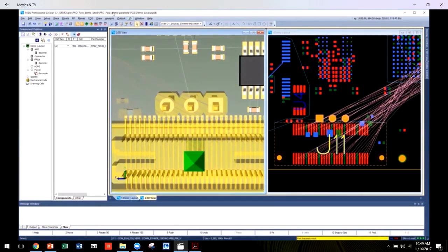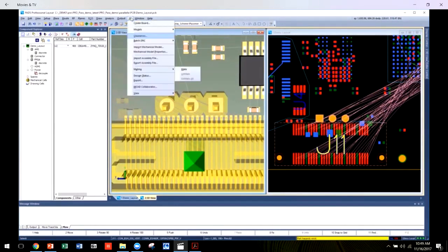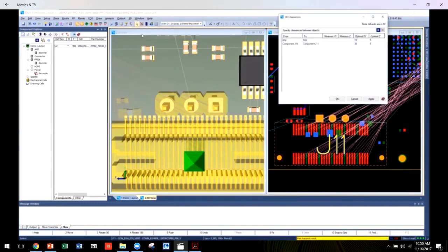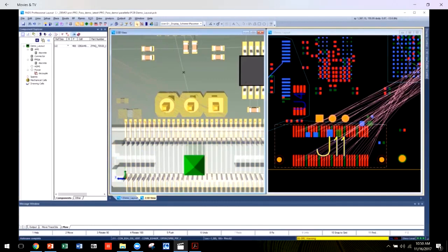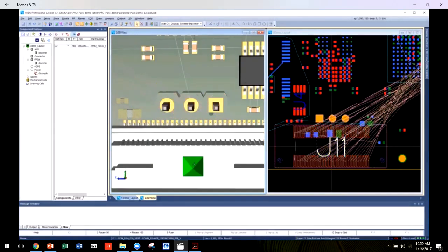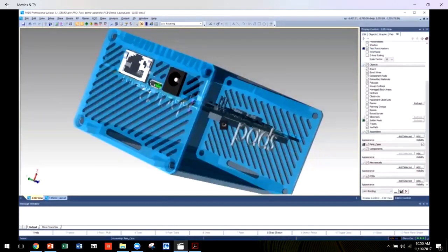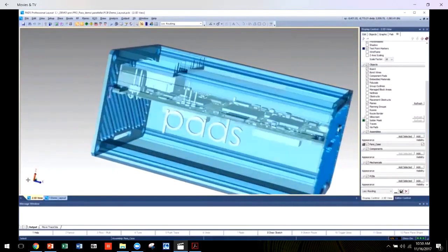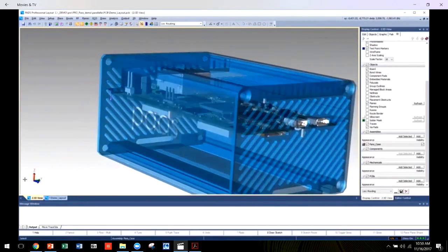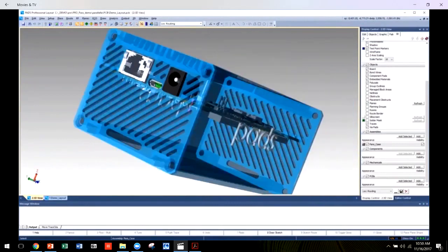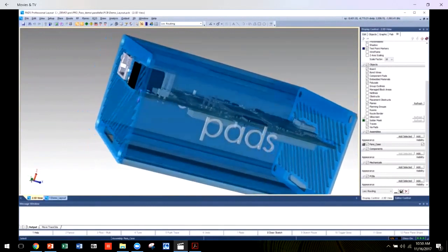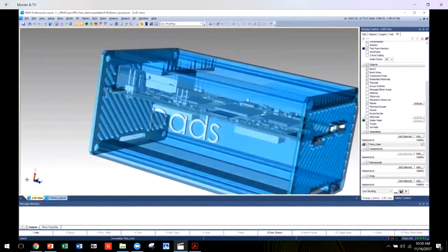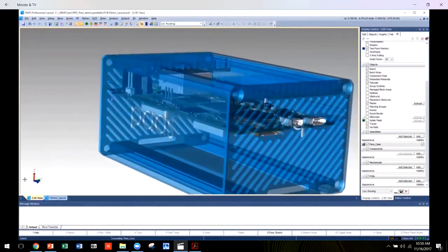To ensure proper clearances between components, set up global and custom clearances between the specific objects and components. Perhaps a connector needs extra space on one side during insertion that is not represented in the mechanical drawing. By viewing the design in 3D, one can visualize how the PCB could be assembled or interfaced with. You are also running DRC verification checks before the system is ever physically created or sent out for prototyping, potentially reducing time to market by left-shifting electromechanical issues earlier in the design cycle.